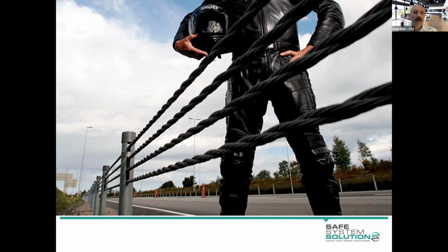The one thing I suppose that the motorcycle community has, which is a very valid point, is that we don't have any really good or tested products to retrofit to this to make it less hazardous. Now, we have in some jurisdictions tried post paddings, so they're kind of like the football goalpost padding. It's not going to be as good as redirecting the energy. You're trying to absorb energy, and it's not as good. And nobody actually has had that tested. And I suspect because the manufacturers know it's not really going to pass.